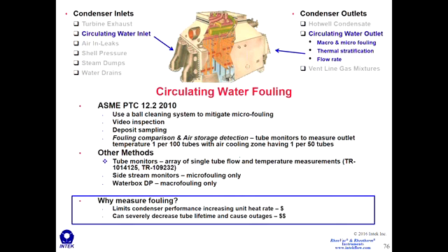So first, let's tackle fouling. Now, the best way to address microfouling is, number one, to monitor it, and number two, to prevent it. Controlling fouling is an endless battle. Water chemistry changes over time, and the chemical process that works today will at some point not be enough. I guarantee that the condenser will macrofoul and potentially go unnoticed until tubes begin to fail.